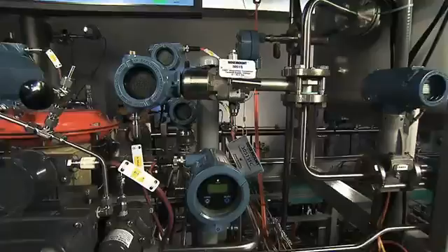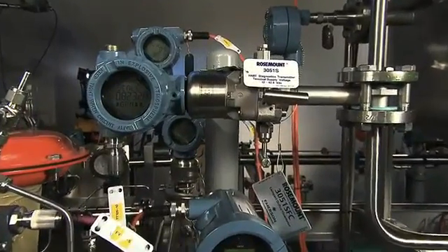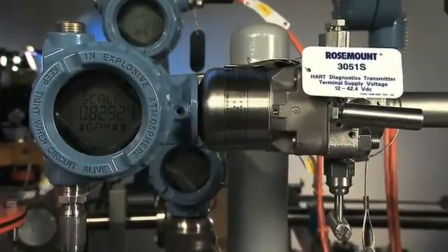Today we're going to demonstrate the power of statistical process monitoring technology using the Rosemount 3051S pressure transmitter. The 3051S is a highly accurate device that's used to measure pressure, DP level, and DP flow. In addition to pressure measurement, it also measures the amount of process variability or process noise.